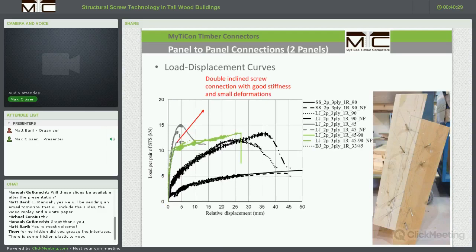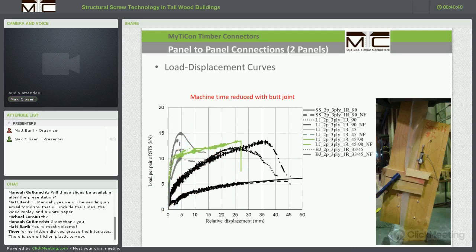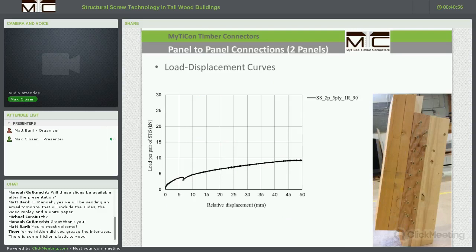For the stitching joint, butt joint, we see intermediate performances. Basically, we have, again, steep load increases with very small ductility at the end. Also, friction does not seem to have a large impact here. So basically we can say there's not a lot of impact of friction in these connection systems from the test data we have for now.